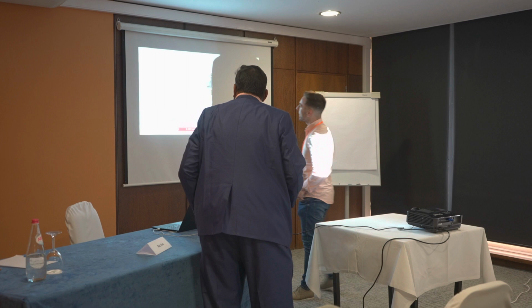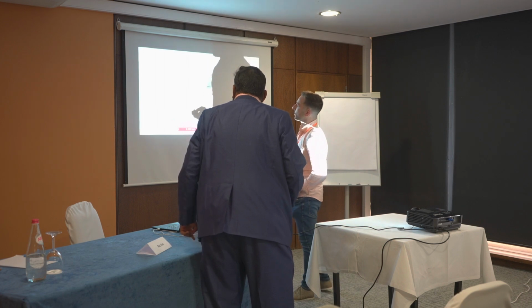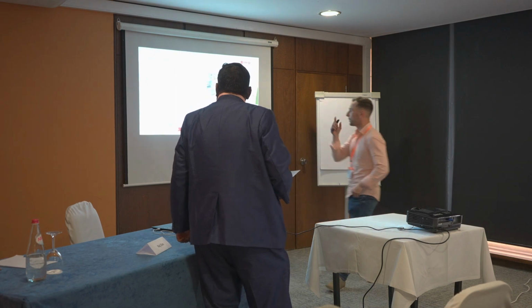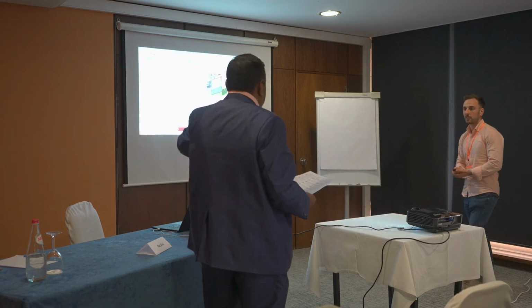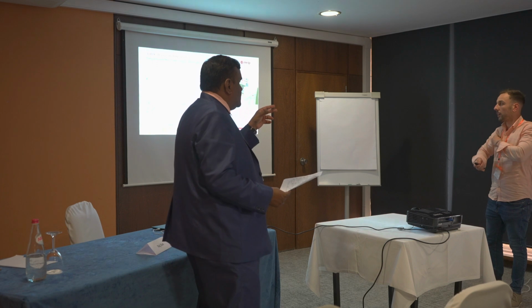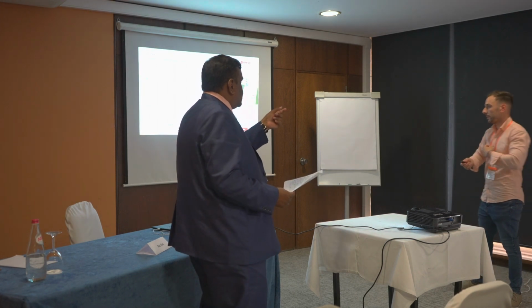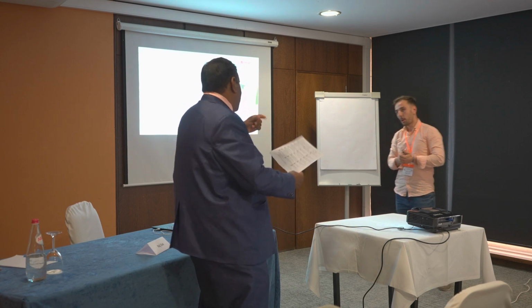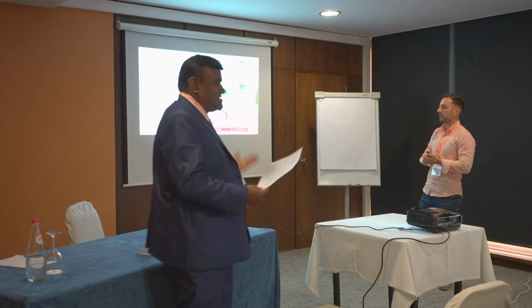Strain, right? This is time and this is microstrain. Yes, you are right. It's difficult to read. But did you have an accelerometer? You could have compared the acceleration with your numerics, and that's the easy way, because strain could be difficult to correlate in dynamic cases.